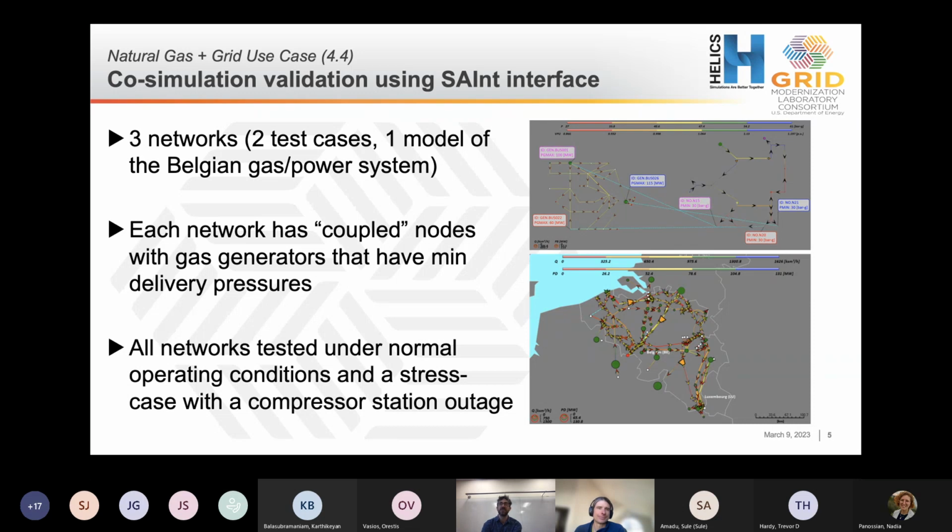But the fuel starvation events were caused by gas wellheads freezing, and I don't quite know how to put that into this model in advance or a priori. Same thing with a lot of the generators just froze, and so that wasn't a gas delivery issue. They got cold and froze. And so I think the biggest challenge is how do you anticipate what those possible failure routes are, and then have the right data to say, well, this is a reasonable outage case. So I think it could be applied for that, but the challenge going from here is getting good data and getting good scenarios to test and assigning some reasonable level of uncertainty or probability to those and that kind of thing.